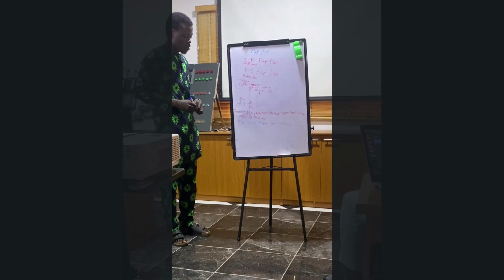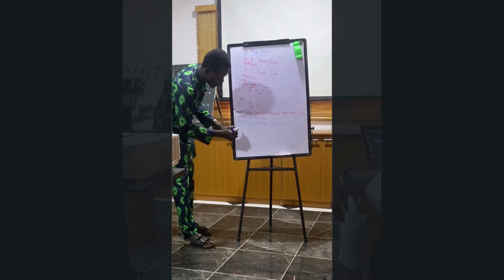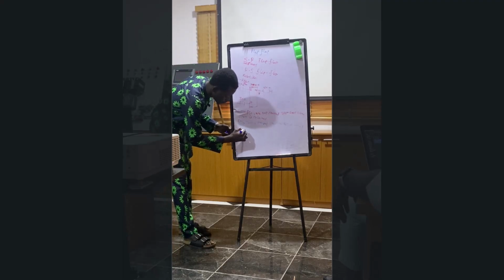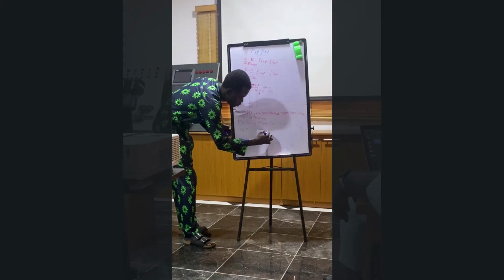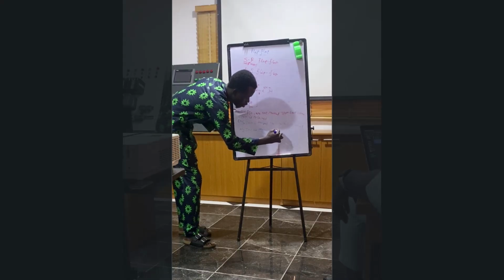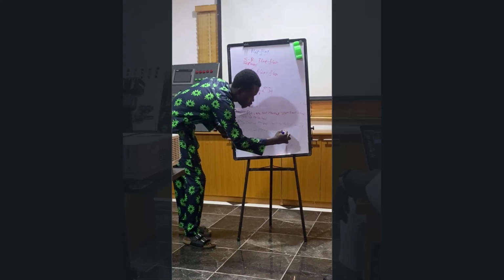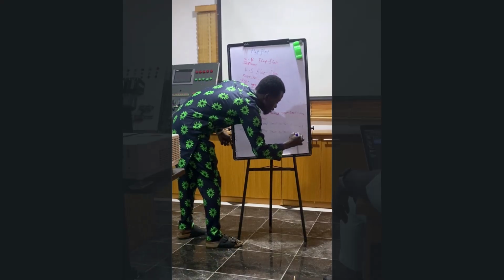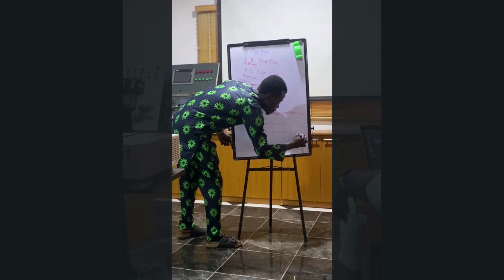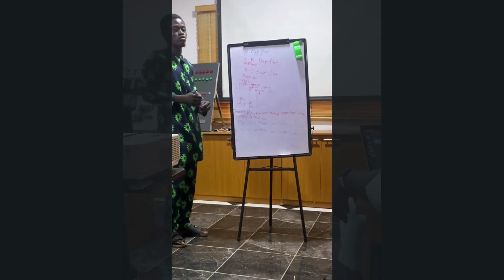Okay, and if only I0.1 is pressed, your output is reset, that is it will be 0.